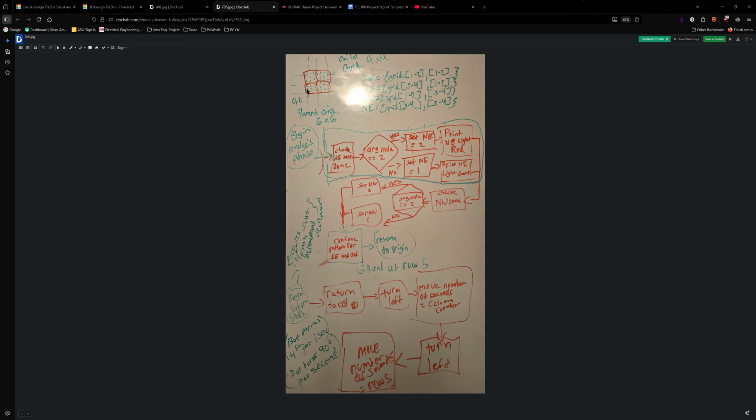Each node is representative of about 4 feet, so every movement burst is 4 feet. It'll stop at a node, it'll scan. If nothing is in the way, it'll move to the next node. If something is in the way, it'll turn north and then move along the grid pattern in whatever direction it was going to go if it had done the entire loop.